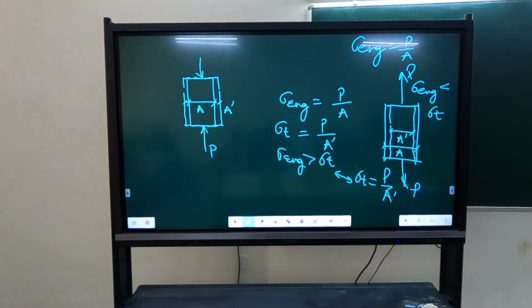Actually, the model which Mander has developed, in that model he considers cylinders. So any empirical formula will depend on the conditions which have been used while deriving that formula. When Mander derived the formula, he used cylinder strength. If you want to use cube strength, you can, but there will be slight changes in the coefficients. There will not be drastic change, but some change in the coefficients will occur. If you want to use cube strength instead of cylinder strength, or the actual strength.